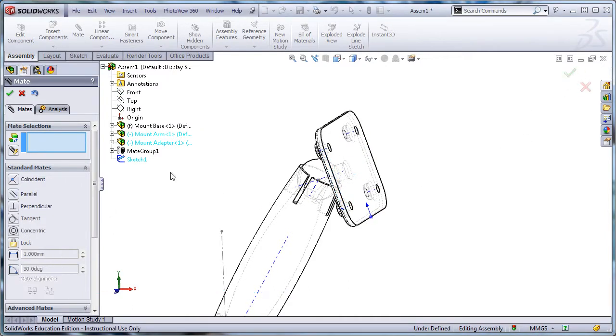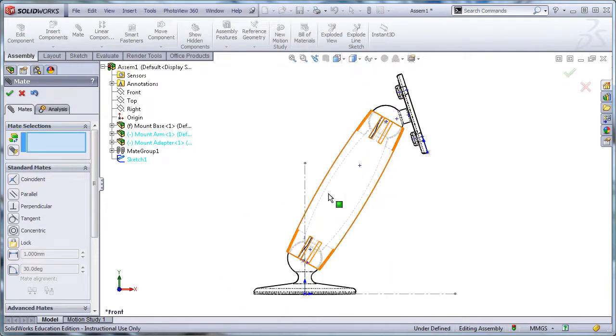Now let's look at this thing in a front view. And we have that profile we're after right there. Okay, so a little tricky. Takes some playing with the mate alignments to get it to look right, but it certainly is doable. The only thing we have is this part spins right now. If you want to pretty that up, then you'd have to create a mate to do so, or you can just eyeball it. Then we can import these into the 2D drawing to make that happen.